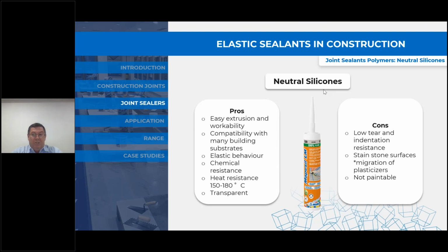When we look at neutral cure silicones, again, the pros: easy extrusion and workability, compatibility with many building substrates, their elastic behaviour, chemical resistance, heat resistance, and again can be transparent. The cons, again: low tear and indentation resistance, so they tend to be soft and not so strong a backbone. The stain of natural stone surfaces, migration of plasticizers can occur, and this is the case with both